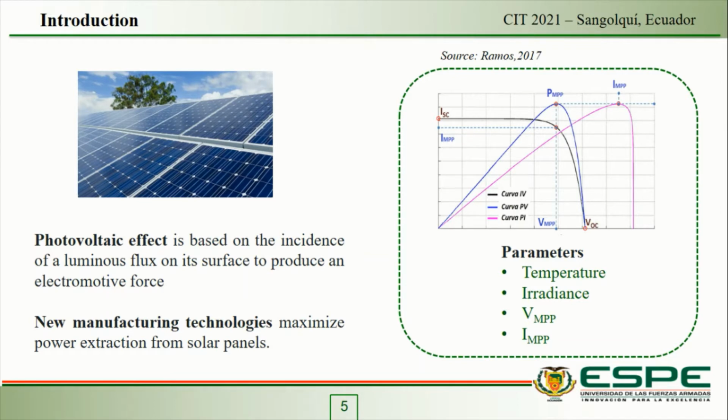The points of maximum power correspond to the place on the power voltage curve where the voltage and the current values are the maximum as a function of temperature and irradiance. A maximum power point tracking (MPPT) algorithm is necessary to implement to cope with variation in weather conditions, ensuring to use the solar energy to its maximum.